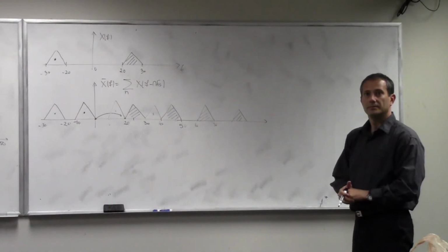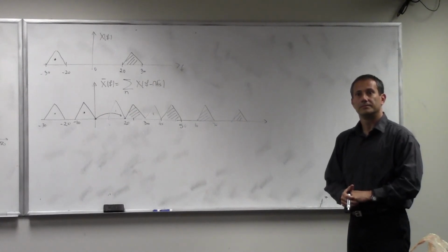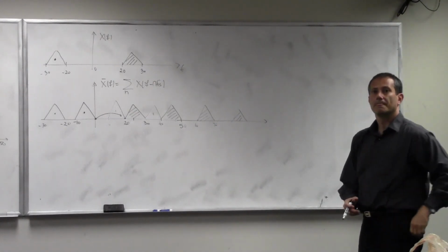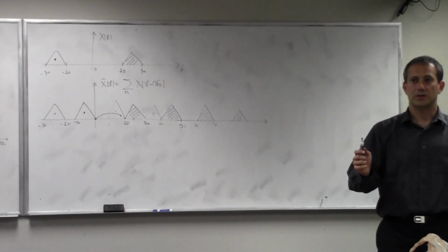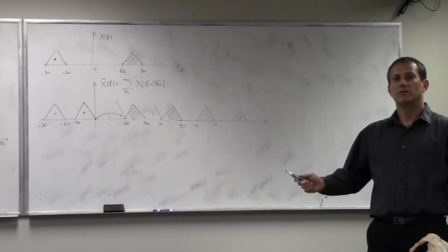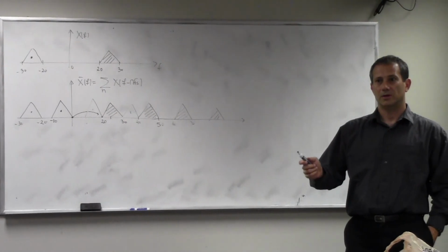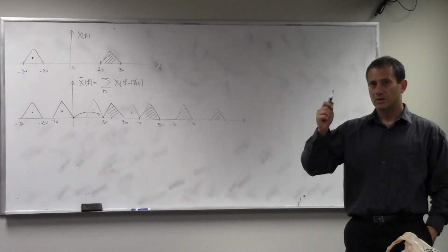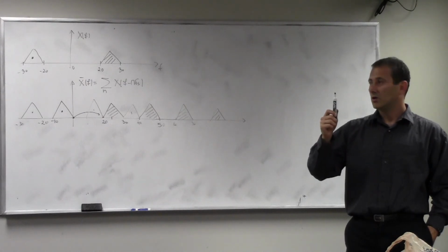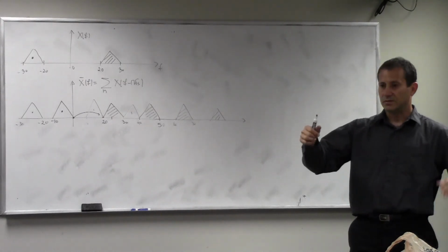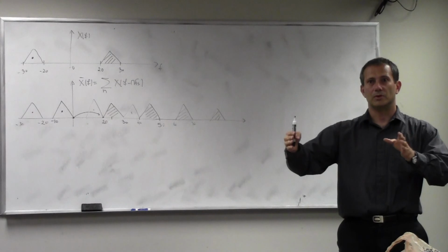So can we just say the Nyquist criteria, because that is the basic thing? Well, this is what I'm trying to stress. This is why all of these derivations are important, because you have to understand what the Nyquist criteria means. It is only applicable if the signal is from 0 to W and so on.